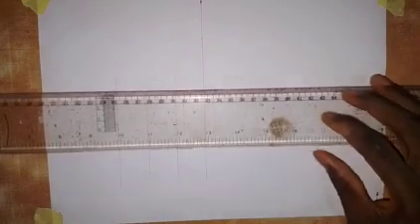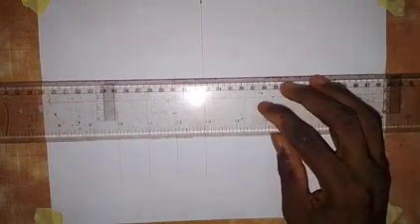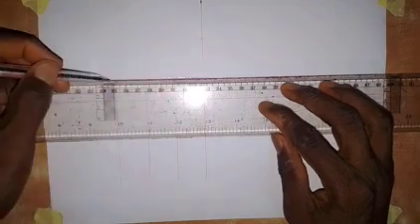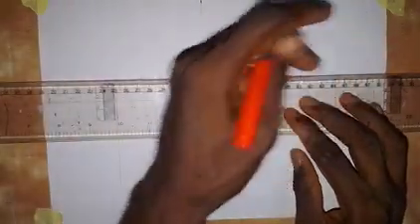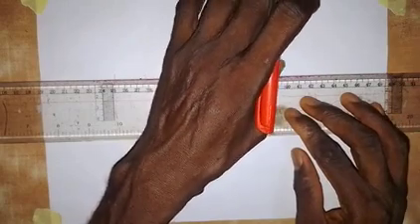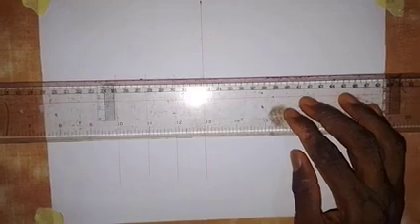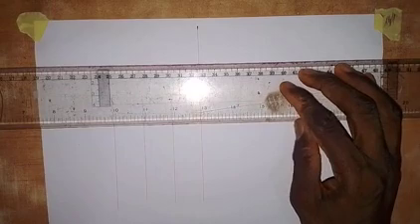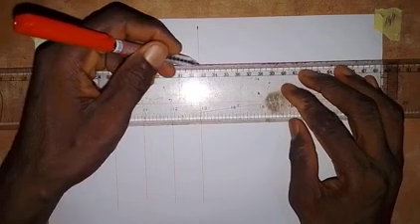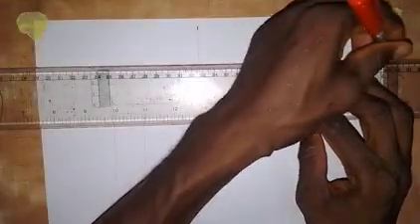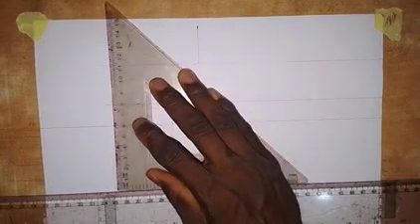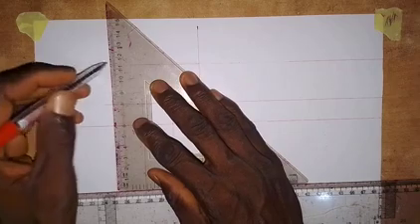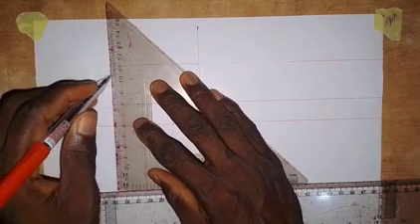Then on the distance that we took on the vertical, we are going to draw a horizontal line all through to this end, and also we take it to this side, because we are placing the left end elevation here on the right side of the front elevation. So at this point we draw the horizontal line to this side and also to this side. For this I need to extend this vertical line here, so it reaches this point.